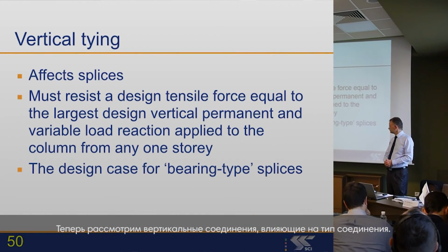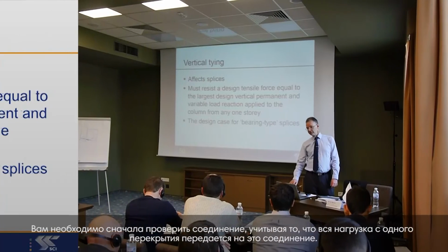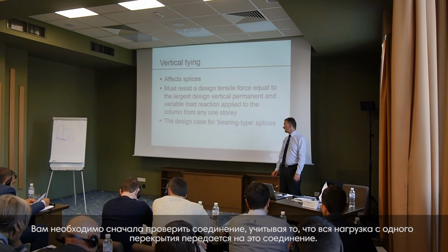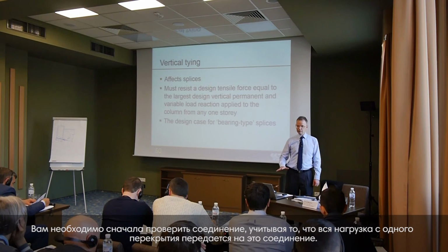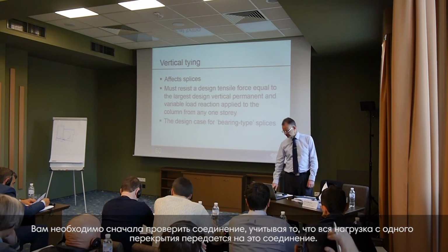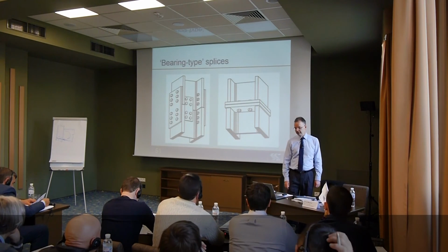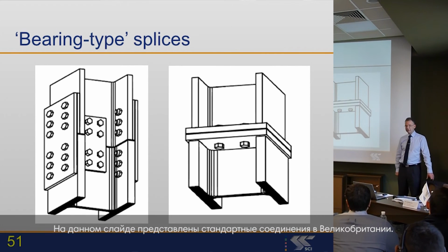Vertical tying then will have an impact on the design of your splices. So you will need to verify your splice, imagining that the whole load from one floor is carried in tension on the splice. So these would be ordinary splice details in the UK.